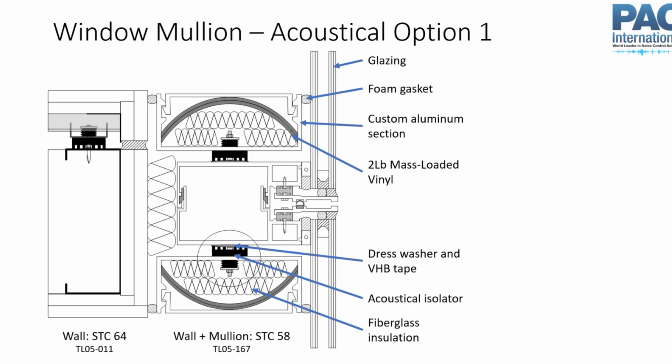There are other situations, like industrial noise control, where mass-loaded vinyl is 100% the thing, recommended a ton for those kinds of situations. But those kinds of things are also not going to give you this acoustic isolation, because you're just going to screw right through them and into the studs to mount your cabinet. And those screws are going to be a rigid path that's going to transmit sound. So you're not really getting any benefit there.